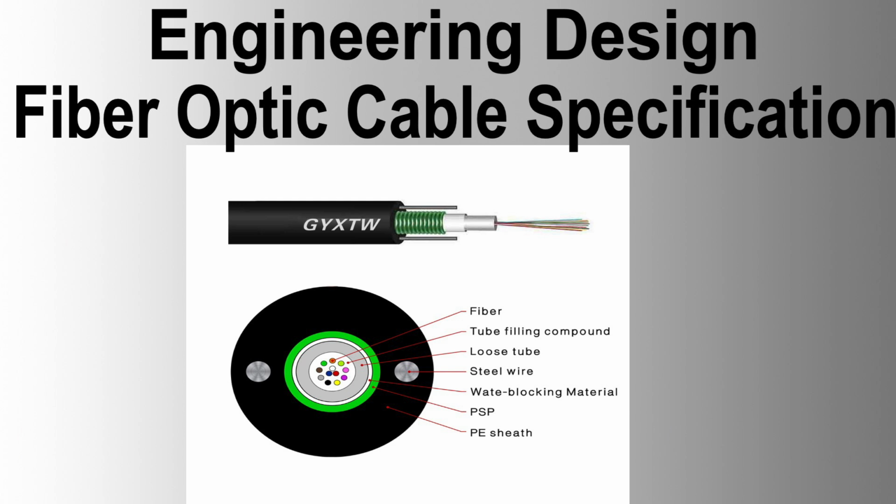Water penetration. A sample of cable must be tested for water penetration to IEC 60794-1-F5B with a 1 meter head of pressure for a period of 24 hours. The water pressure shall be applied to the cut end of the cable in an L-test configuration.